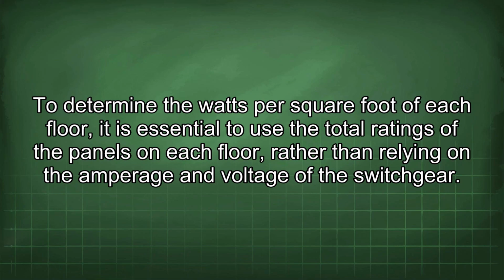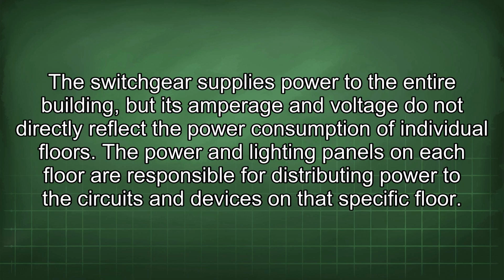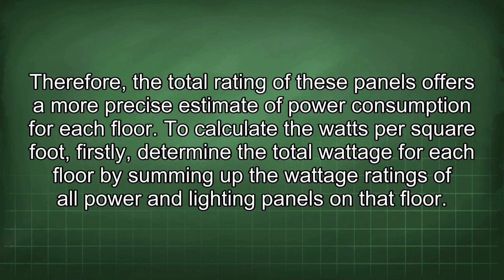To determine the watts per square foot of each floor, it is essential to use the total ratings of the panels on each floor rather than relying on the amperage and voltage of the switchgear. The switchgear supplies power to the entire building, but its amperage and voltage do not directly reflect the power consumption of individual floors. The power and lighting panels on each floor are responsible for distributing power to the circuits and devices on that specific floor. Therefore, the total rating of these panels offers a more precise estimate of power consumption for each floor.